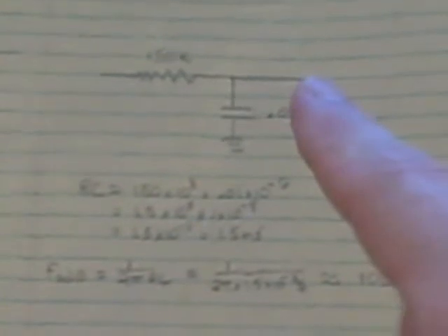And so you'll see the signal that you put through mostly on this side. As you increase the frequency, the little wiggles in voltage can induce wiggles in voltage on the other side through the insulating material. And so if you get the frequency high enough, the electricity basically takes the shortest route to ground and goes all through the capacitor. So if you're looking at the signal here at very high frequency, you don't see anything. So essentially this is a low-pass circuit.